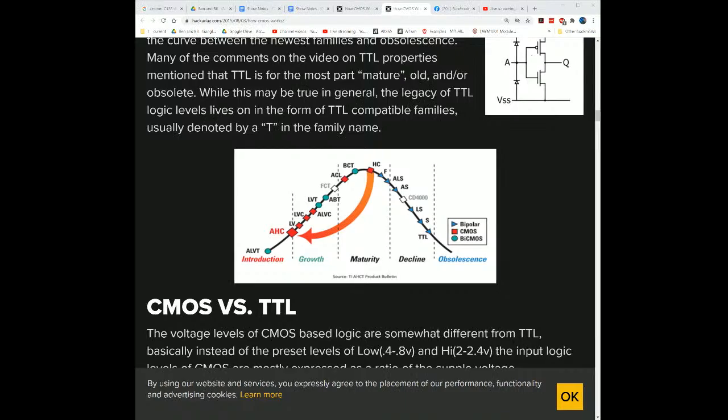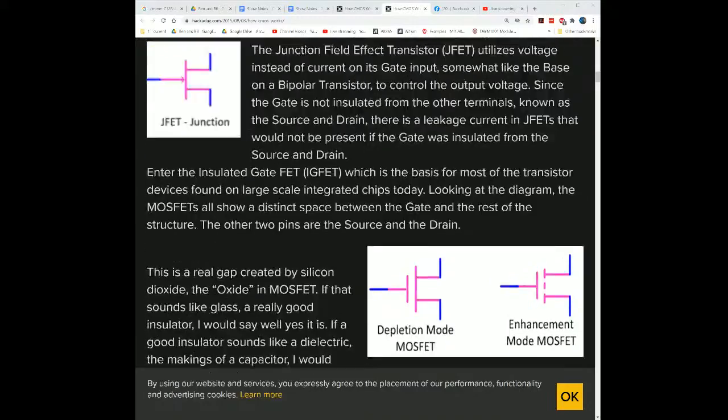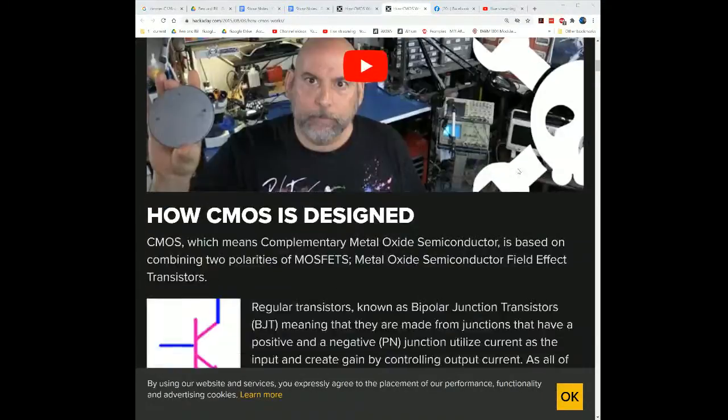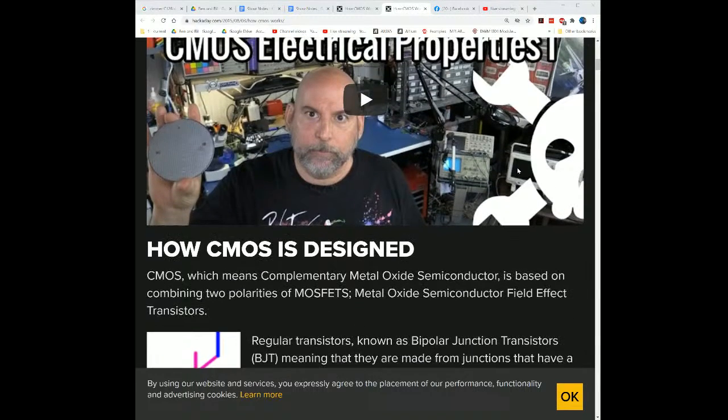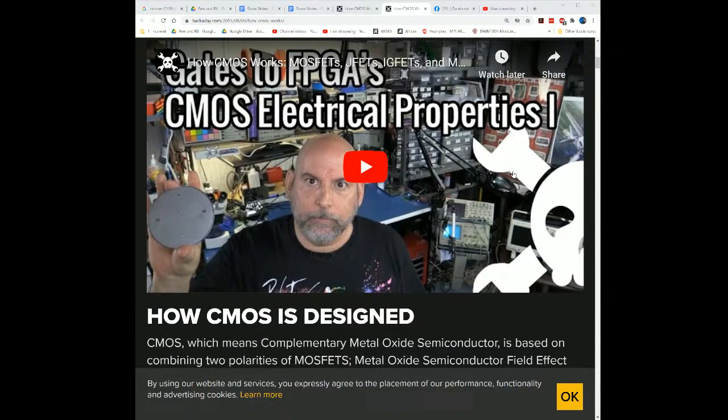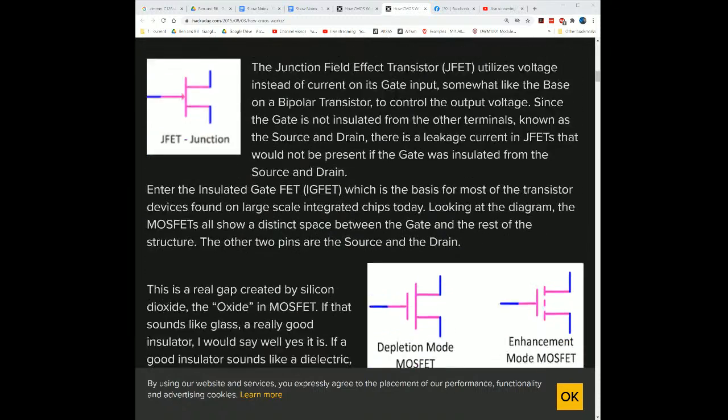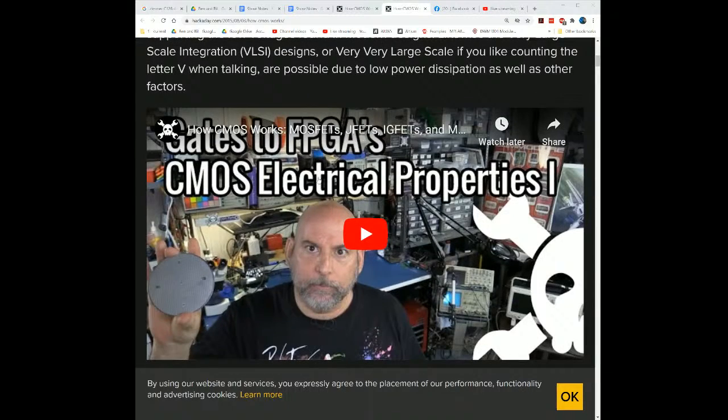Well, basically, I was talking about everything CMOS and layers and everything. And so I actually show a wafer. That's an old wafer, a 5.5-inch wafer. The wafers these days are like dinner plates. That's kind of a, well, for yield, if you're going to do 28 steps, including photo etch, photo resist, washing it away, exposure, running x-rays, you might as well do it to the biggest piece of something that you can afford to produce.